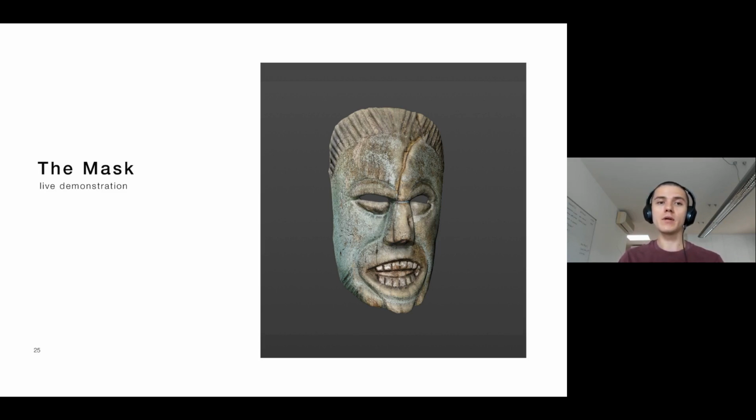Another example. Something else you could do, if you have a flat surface that has little to no detail, is add some X's. You can use a marker or some black tape, let's say, and put little markers on the surface, so that when you're taking the pictures, the software can recognize the actual flat surface.